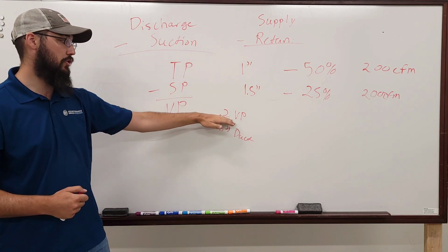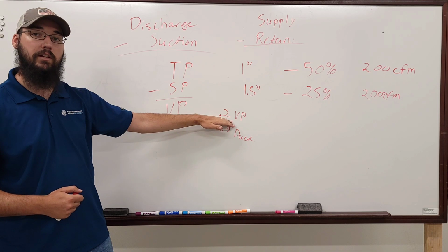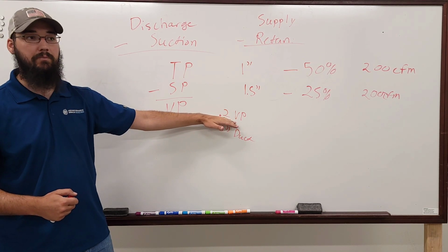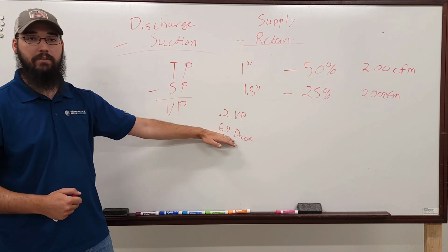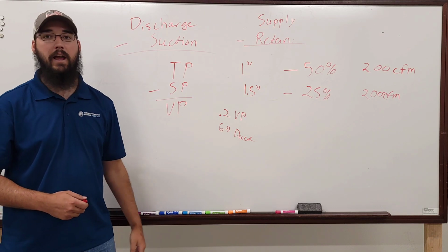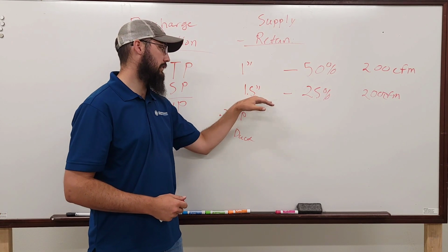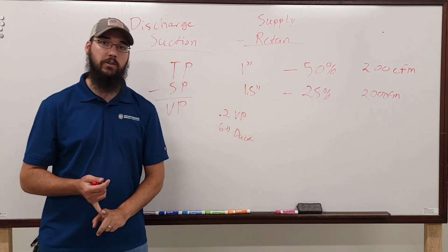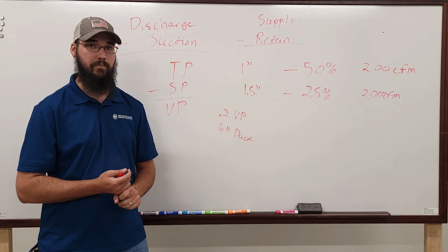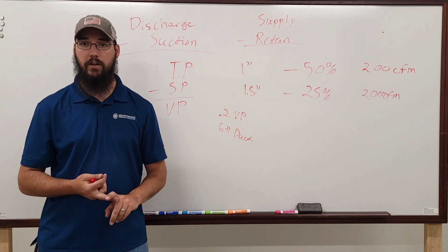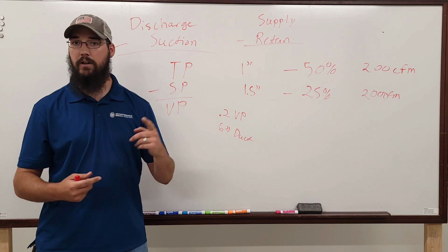But as the controller inside of that VAV, it just sees I have a 0.2 VP, and I know that I'm programmed to have a 6 inch inlet duct. I know that that's exactly what I'm being asked to do right now. By increasing this pressure, the only thing you do is you lose efficiency on the motor and the whole system. And you put extra wear and tear on the drive components, on the motor itself, on the blower, the bearings.